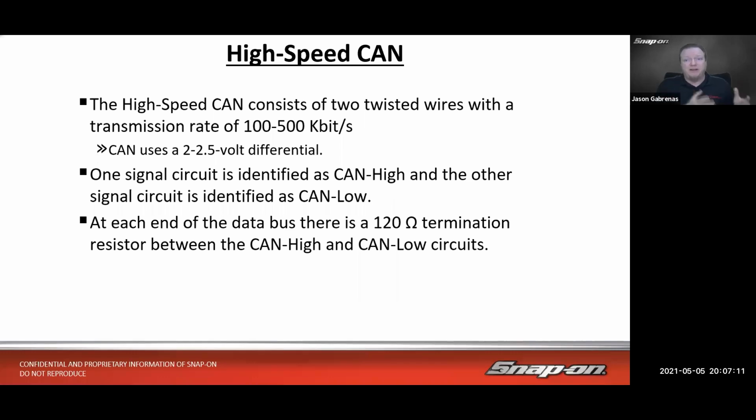I think back to my days at Subaru, we had an alarm upgrade for a glass break sensor, and you had to plug that into the CAN network. It was optional, so it was a dealer-installed accessory. It was underneath the seat. There was an open CAN bus cable connector. You would remove the 120 ohm resistor, plug in the module, and then it would power up. You have to configure it, of course, but it would be up and running. That is just one example.